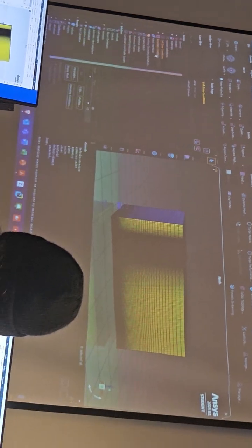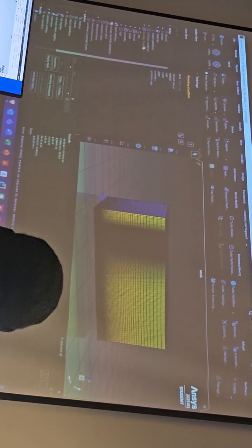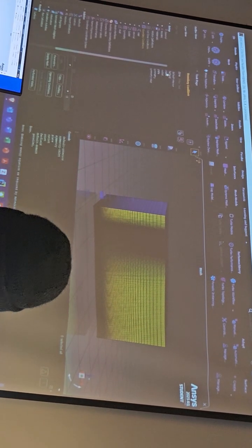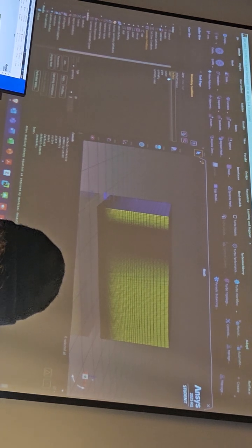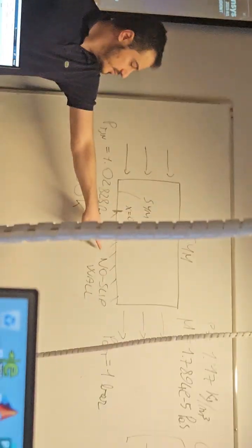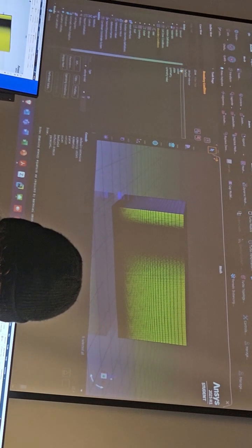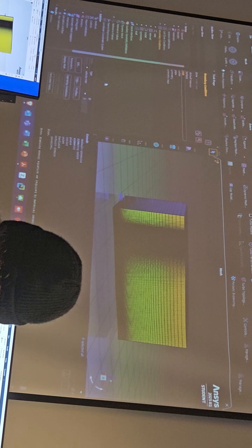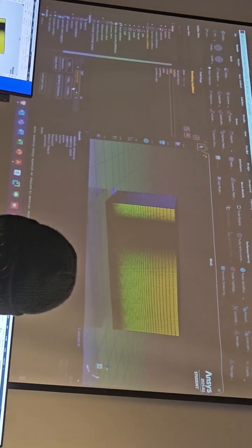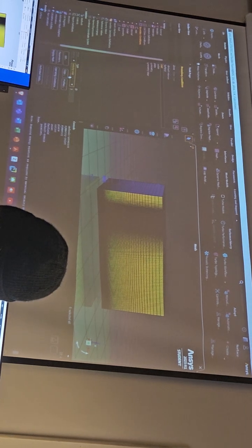And then the next thing we can do is in boundary conditions. We can set the boundaries, so the ones that are shown there. The far field is the surface at the top, farther away from the plate. This is a symmetry. We set it as symmetry, so by default it's already symmetry here. Inlet is set as a velocity inlet, but we know the total pressure and total temperature there, so we change the type of this to pressure inlet.